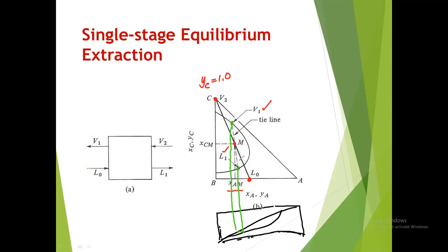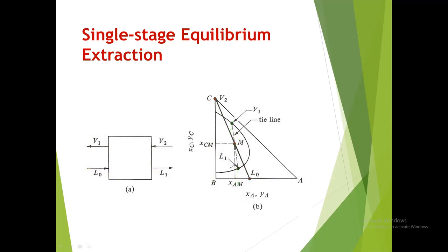Okay, so then this is one stage. The way we count the number of stages, graphically, for liquid-liquid extraction is by the number of tie lines that we produce. In this case, since we're talking about a single stage extraction problem, this is your one tie line because you only have a single stage. Now, in terms of determining the concentration of V1 and L1, it's a simple case of read out. I'll just erase the marking. You're just simply going to read the concentration here. For L1, you have your XA1 here.